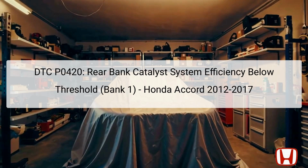Upon detecting a performance drop, the Powertrain Control Module, PCM, initiates an air-fuel ratio adjustment, monitoring the fluctuations via the secondary heated oxygen sensor located at the rear exhaust section. When the performance parameters exceed predefined thresholds, the PCM stores the DTC and alerts the driver that further investigation is necessary. Proper understanding of this code is crucial for efficient repair and maintenance of the vehicle's exhaust system.